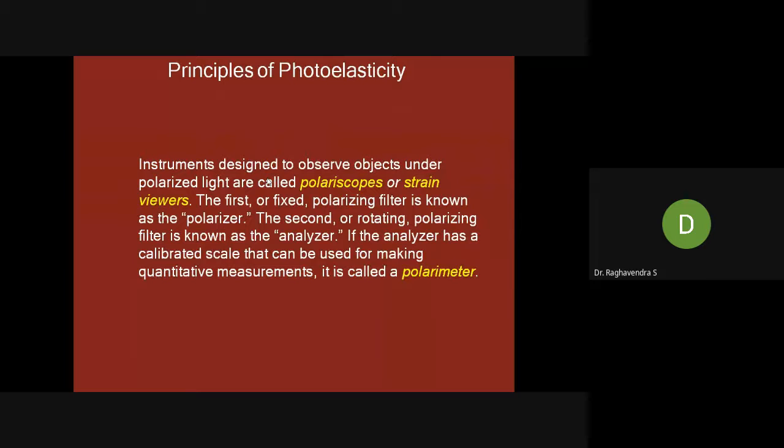In the eighth semester you can realize there is no equipment in your laboratory to measure stress directly. We are calculating the stress from the strain. First, you calculate the change in length by the original length. Then you get the strain. We know the Young's modulus value of the material. Then we calculate the stress. This is how you do it.